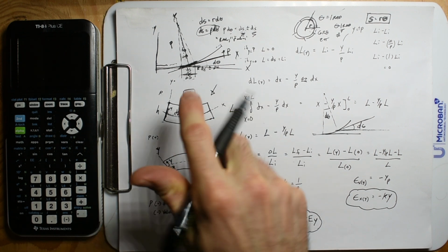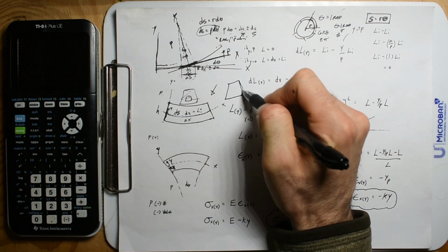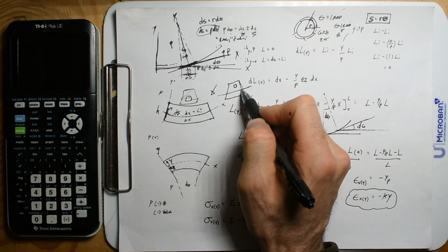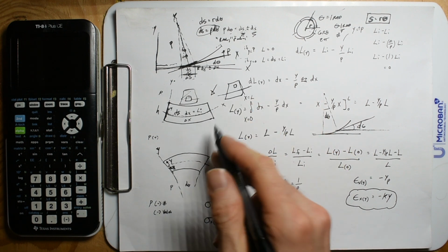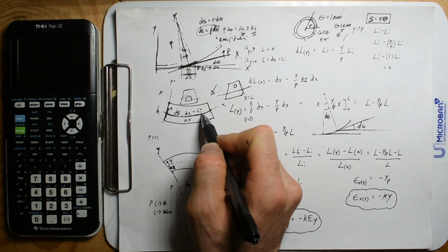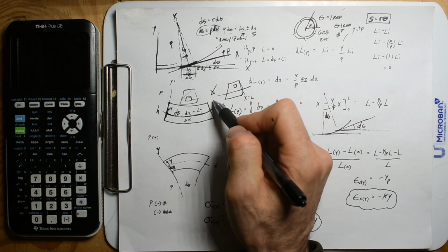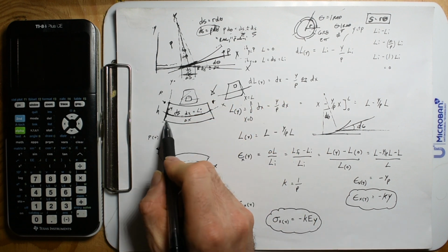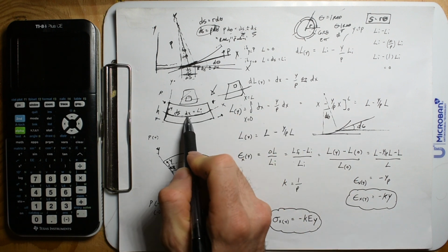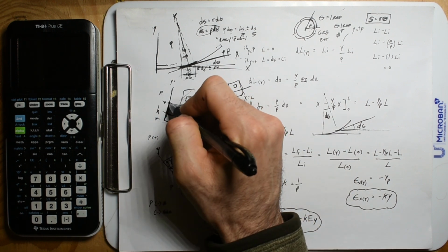Cool. And the cross section of the beam is shaped like a trapezoid for this problem. One of the principles is that there is going to be a neutral axis where a beam in bending, like these parts get compressed, the bottom gets lengthened. Now maybe you don't know where that is, but we do know there is a location, and that's where we put our coordinate system.